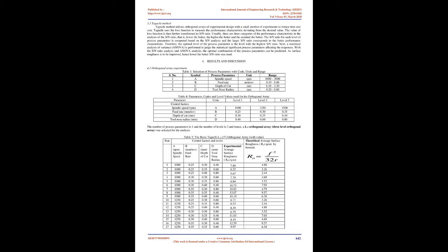Ali Reza Motorco [3] investigated surface roughness in turning of AISI 8660 hardened alloy steels on CNC lathe by ceramic-based cutting tools. Cutting speed, feed rate, depth of cut and tool nose radius was used as cutting parameters. It was concluded that feed rate was found to be the dominant factor among controllable factors on surface roughness followed by depth of cut and tool nose radius. Cutting speed showed an insignificant effect.